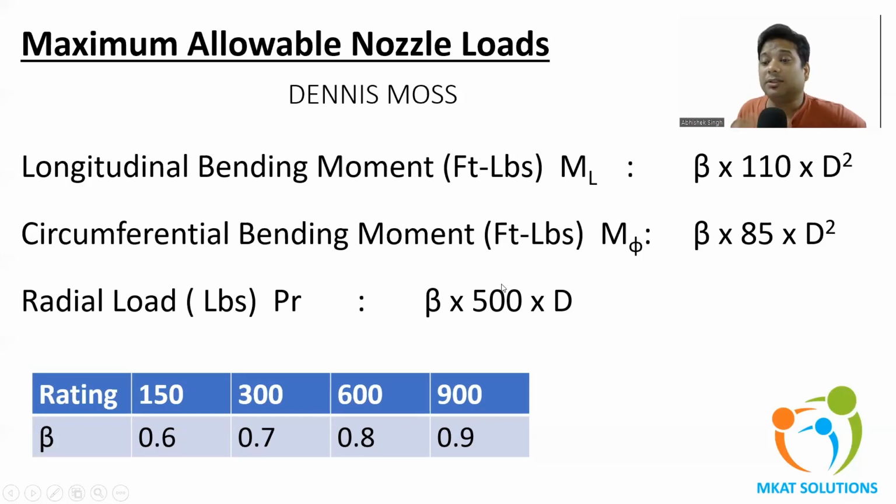Now you will see that there are other loads, the torsion also, which is applicable. But torsion does not affect the stress value to a great extent, and that is the reason those values are ignored. We have not considered those values, because finally the shear and torsion effects are negligible in the final stress outcome. So we can eliminate them. These are the major loads which we have to deal with.